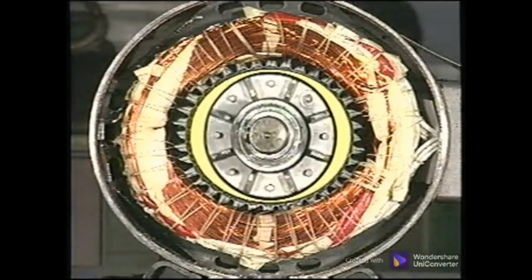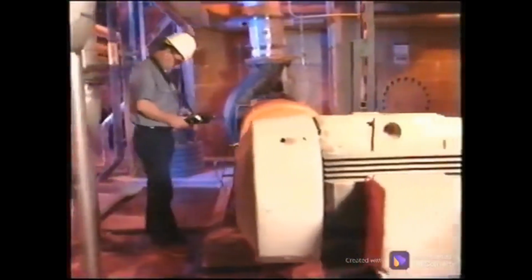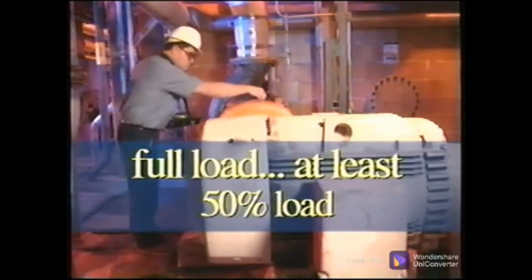It would have the highest amplitude in the direction of the eccentricity and much lower in the direction where the air gap is equal on both sides of the rotor. To capture these problems in vibration data, 2 considerations are required. First, the motor should be running at full load or at least 50% load. Without a full load, the stresses are minimized and problems are masked.